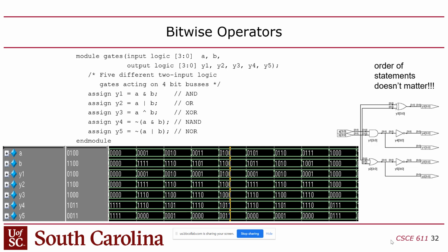Notice I've got a module here with 2 inputs, A and B, and they're declared as input logic 3:0. There are 2 problems with this. Number 1, why 3:0? Obviously that's meant to represent a 4-bit signal, but in any other language, you would just say 4 bits. Why does it have to be a range? Well, that's just the syntax. But the bigger problem, in my opinion, is that the number of bits comes before the name. If this were C, you would put the size of the array after the name, not before.